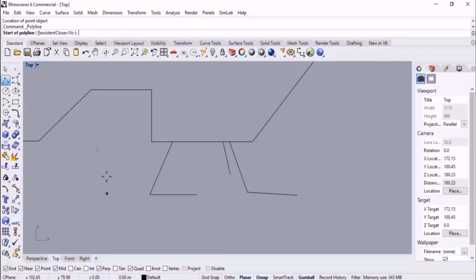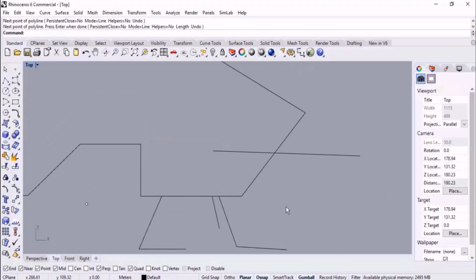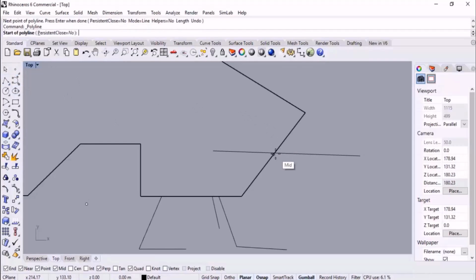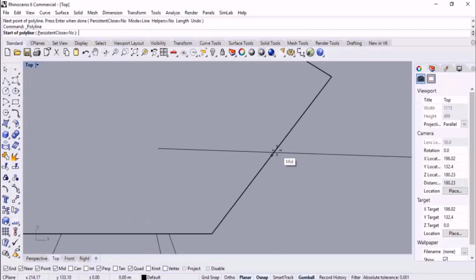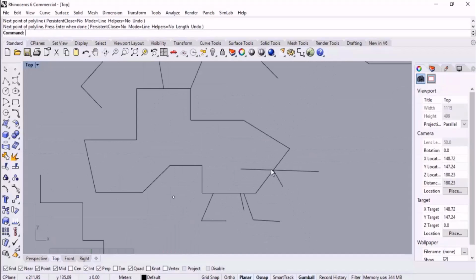And about point, it constrains the marker on the points. As you can see, check this out. And midpoint object snap, I explained it. Center is used for the circles and the curves, that it gives us the center of them. INT or intersection object snap, it gives us the intersections. If I sketch a line like this, then we can have the intersection between these 2 lines. As you can see, here we got the midpoint, and I activate intersection like this, and then it constrains the marker, so we can start a line from there and sketch the line from the intersection.